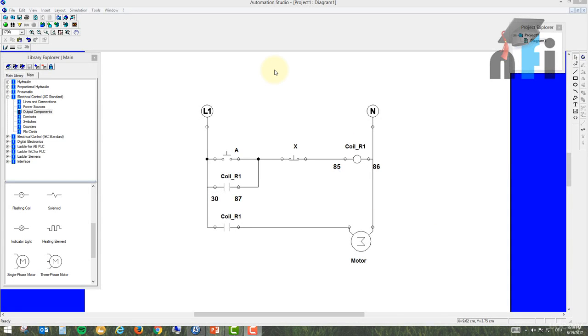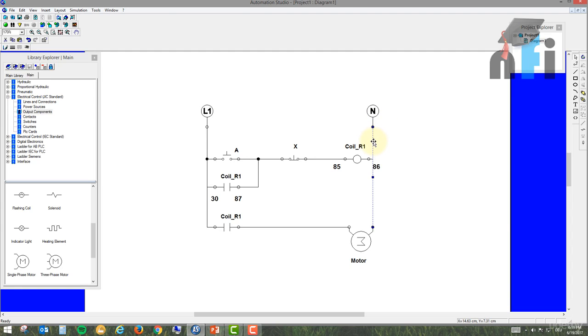All right, before we move to the next video, I forgot to mention that in case you have a coil which is energized by a DC voltage, because we have two types of coil, one AC voltage and one DC voltage. If you have the coil or relay which is energized with DC voltage, in that case you don't have to connect line and neutral because this will damage the relay. So how you will change the circuit is, all you have to do is just connect your latching circuit with 24 volts and your power circuit with line and neutral.